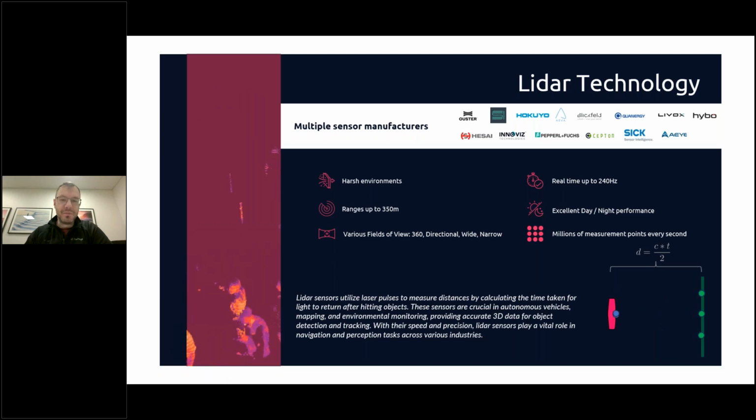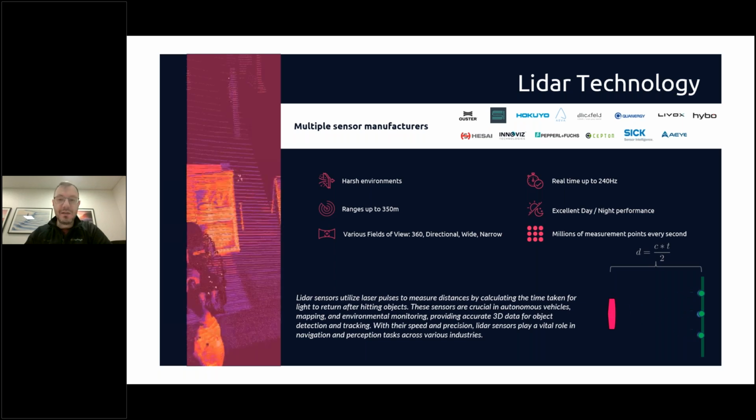They have different spectrums of range, from short range to long range sensors, but we used to say up to 350 meters. Of course, you can find LiDARs which exceed this range much more, but this is a range where we can be certain that you can get proper detection, proper notification, considering the vibration and all those kinds of aspects. So we used to say 350.